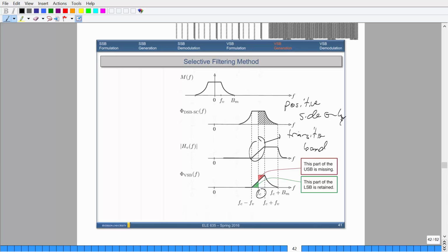And then if I applied a correct bandpass filter, this is one example of what a vestigial sideband will look like. So anything after the carrier frequency here. Remember, this is the carrier frequency, and this here, f of v, you can think of as your f of 1 from before. If you were to actually filter this out, notice that the carrier frequency is right here, in between the transition bands. So in between is the carrier frequency, and you can consider this as f of 1.